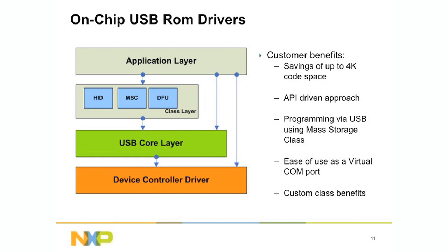Okay. So USB ROM drivers. This is a block diagram. This is what it basically looks like. And like I said, some of our parts have USB ROM drivers in them. It's a good idea to use them. It saves space that you would otherwise like to use for your programs. So we encourage you to use them. And in fact, USBlib actually works with them nicely. All you have to do is set one little switch in the library, and it'll revert to using these drivers instead of using its own drivers.